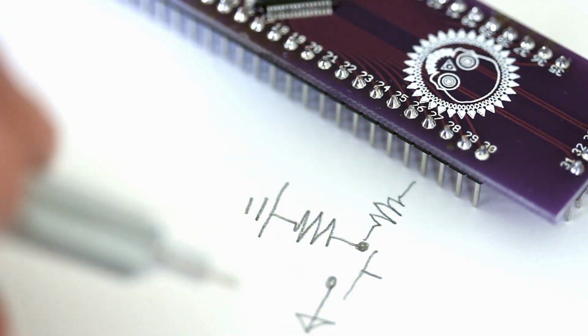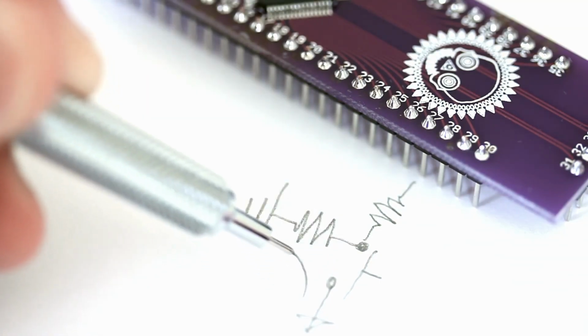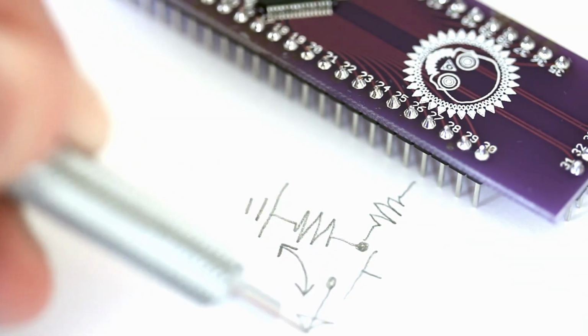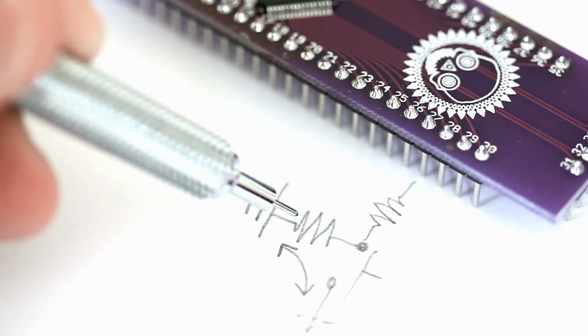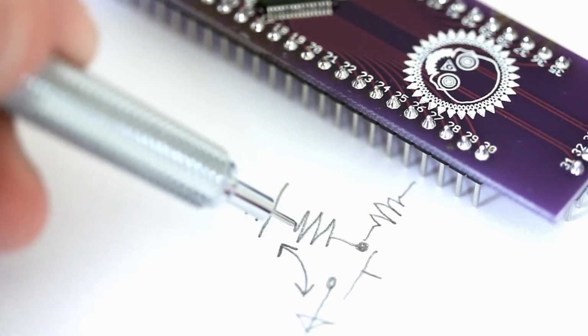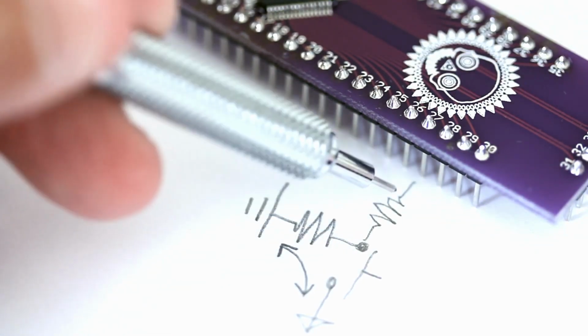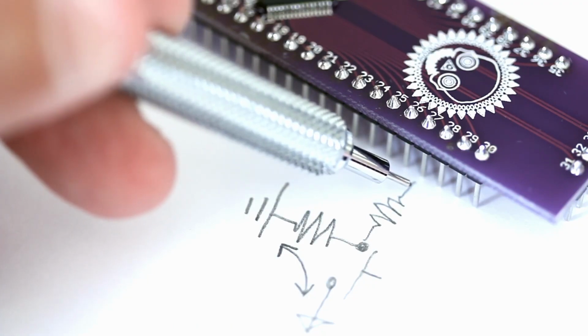So in the pressed state, you're going to have these two connected. So you're going to have a connection between ground and VCC, which will be at 220k ohms, which is high resistance. So very little current is being used when we're pressing the button. But it's also connecting to the pin at a 330 ohm resistance. So we're protecting the pin, but we're still getting the high signal from VCC.